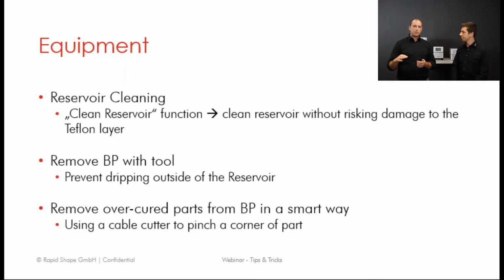You can leave that sheet in there whilst you clean out as much of the liquid resin as possible, and then right at the end you can peel this off without feeling like you've damaged the Teflon layer in the crucial build area. Now this is applicable on the 30s and the 40s or the 20s. It's universal. Okay, so then the next thing would be the build platform removal tool.